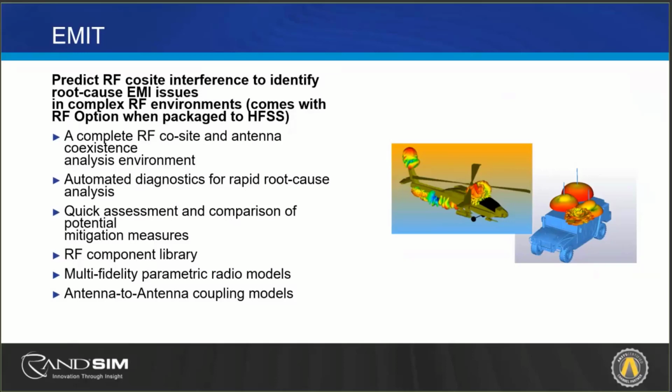And really what's interesting about emit is it allows you to look at the root cause of where the problems are coming from, whether it be in this 3D geometry or trace level on a PCB, and you can quickly analyze your PCB or your 3D geometry and move, or in the case of geometry, via fence or add other techniques to solve your EMI issues.